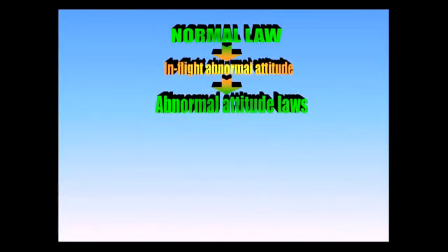During recovery, pitch reverts to alternate without auto trim or stabilities. Yaw becomes direct. Roll also becomes direct. Only load factor protection is maintained. After recovery, the airplane remains in pitch alternate law, yaw alternate, limited yaw damping, and roll direct. However, there is no reversion to direct law when the gear is extended because the abnormal attitude law retains the flare mode.